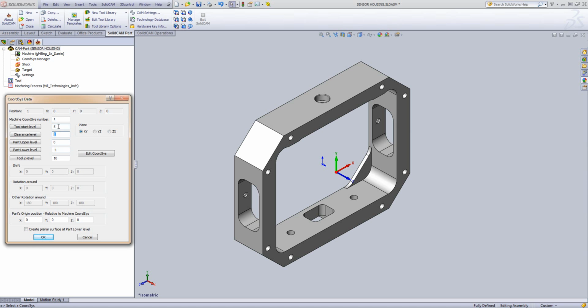The tool start level should be set to 5 per the first video called the settings. The tool start level should not be turned on in a 2 or 3 axis post unless requested. This value is used for a special tool change point. I like to set it up and out of the way of the clearance level. If the clearance level ever exceeds the tool start level, you will get an error message and may not know what it pertains to. If everything looks good, select OK.